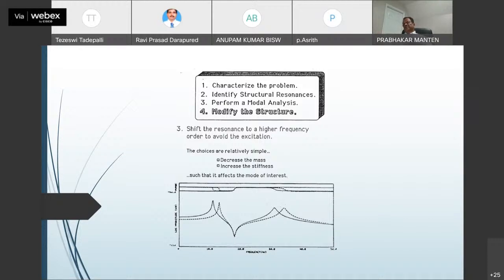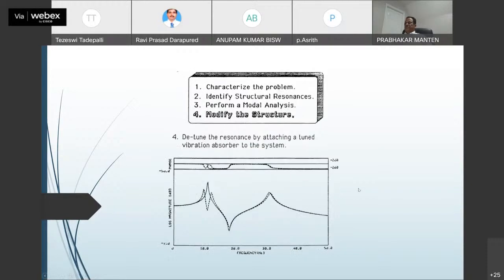Composite materials like carbon fiber epoxy and glass epoxy have a high stiffness for a relatively low mass. Their stiffness-to-weight ratio is really good. So you can achieve those not just by changing materials for a given structure. So detune the resonance.